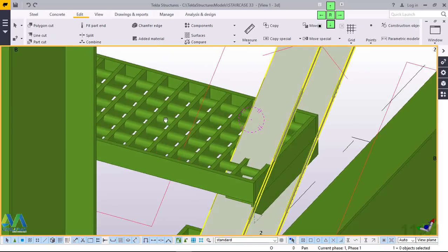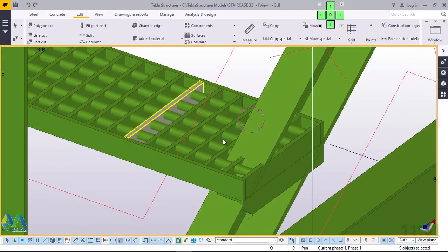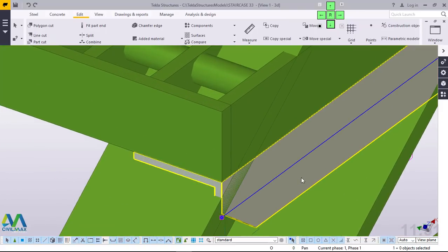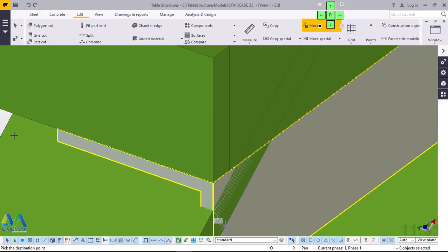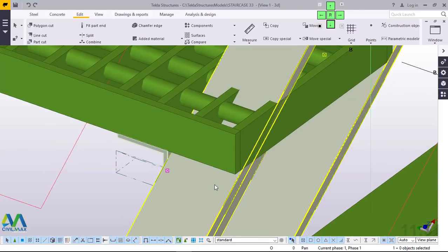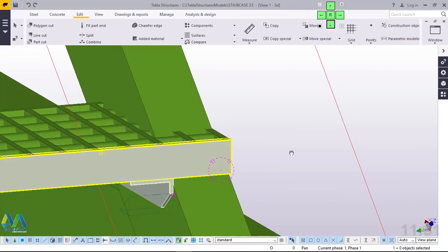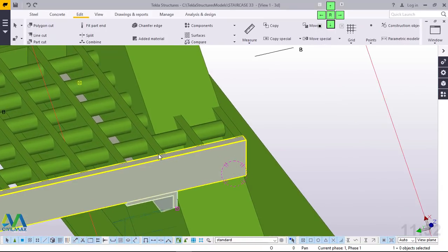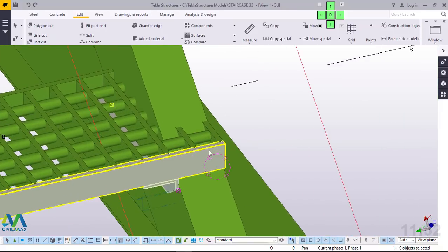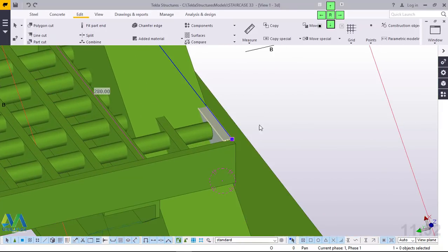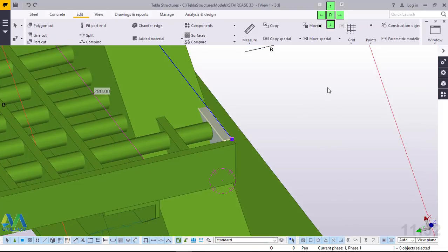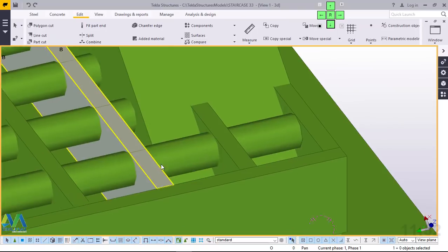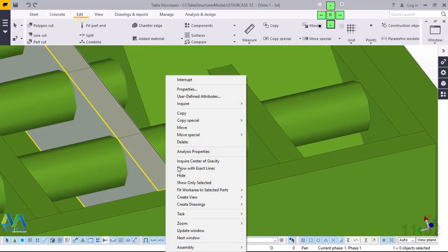Then I turn this round. I'll click on this, right click and come to Move. Snap right here and turn all the way and snap on that end to be supported at that end. Turn that round. Once I'm done with that, I'll click on this, right click and delete this. Click on this member.